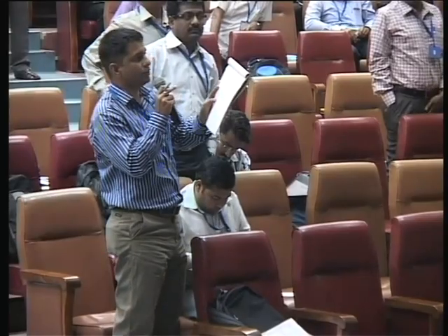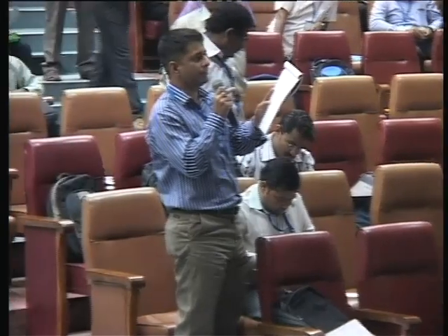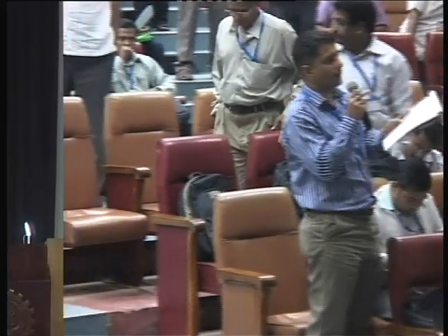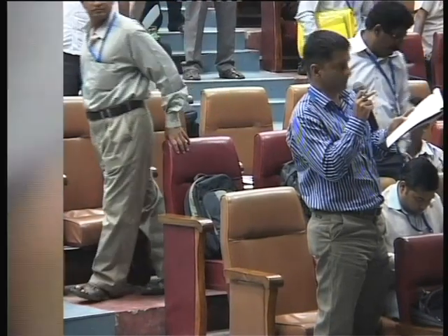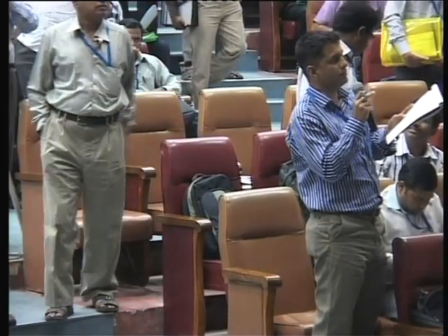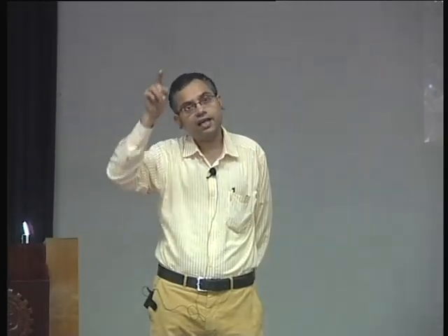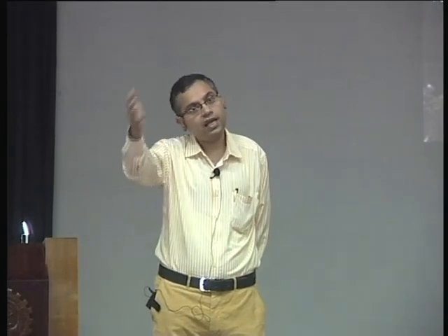So then capital D Dt is del del t plus u del del x plus v del del y plus w del del z. That is the first term. Second term is the divergence of velocity vector. So change in volume per unit time is the divergence of velocity vector. That has been derived. So divergence of velocity vector is del u del x plus del v del y plus del w del z.